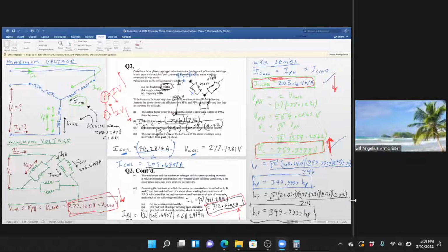That's the minimum voltage. And the part 6, we already did that. I don't have to do that because we did that a couple of times. We did that extensively. Find the ohms when all the coils are healthy, and when one is shorted and when one is open. And I even did it when there were 2 shorted and 2 open. So you should know that pretty good.